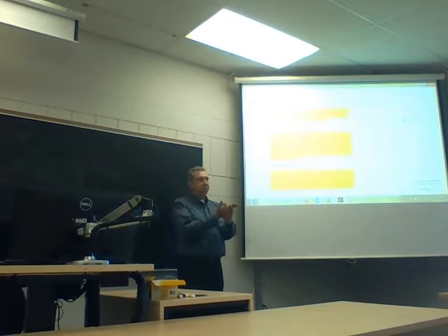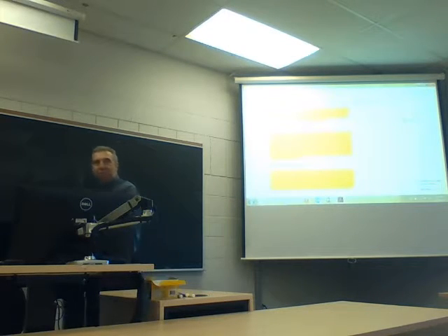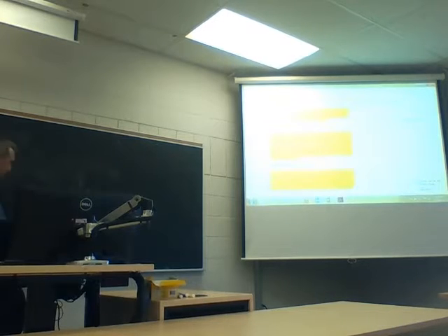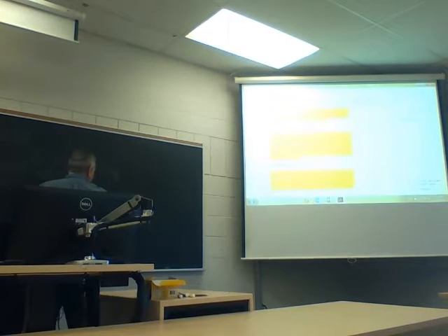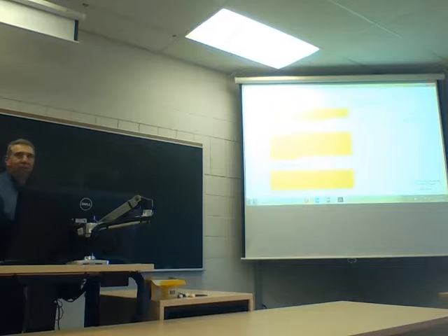So there are actually open ports. As it spirals, it opens a little bit of the port, more of the port, more of the port. Got it? Gradually, so it's basically got a screw. We've got a port here and a port here. As it starts to screw, it will open more and more of that port. So that's how they can use it as a control.